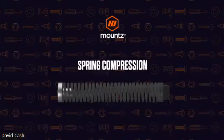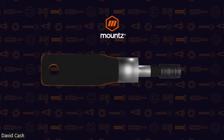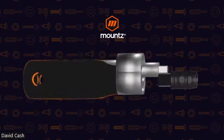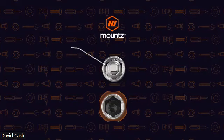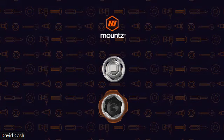In most cases, we are compressing a spring in the torque delivery, and how that spring gets compressed is the difference between different brands of screwdrivers. If we take a look at the system that we use, we have a radial cam that has 6 different lobes within that cam.